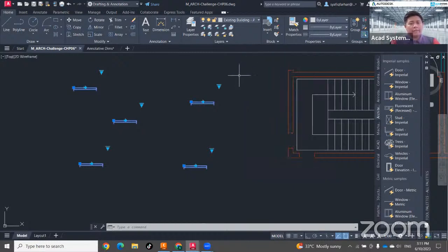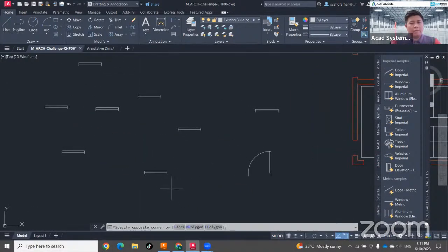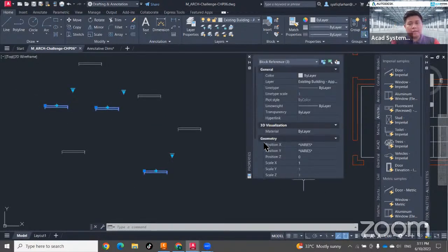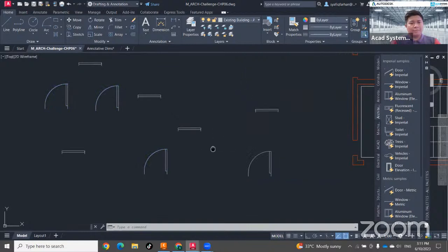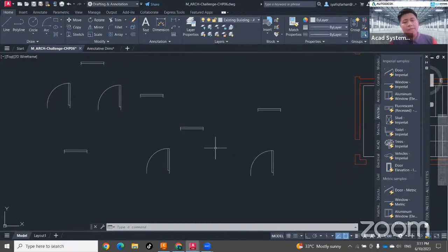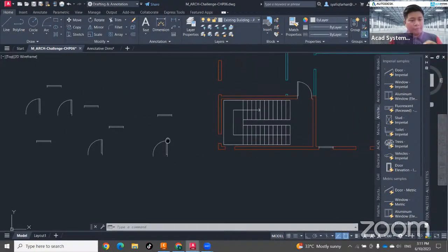Okay, and next, if I want to make it a few only, then I need to make it by selection. For example, I have a few more here. If I want to select this one and this one to become open, it's just the same process. Go to here, use door open. Okay, it's much faster. Instead, if you need to delete or replace blocks, you will have a lot of work later. Okay, that is the most efficient benefit of using this method, right?